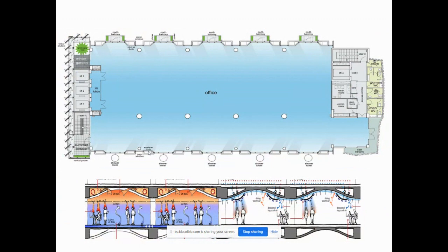They wanted an open plan, and therefore, we wanted to create a ceiling which would absorb heat from people and absorb heat from machines, and we would cool that down by opening windows at night. And then underneath the ceiling, we would have chilled panels, with cold water.